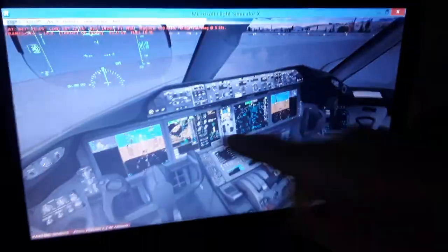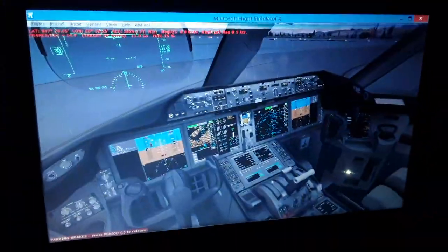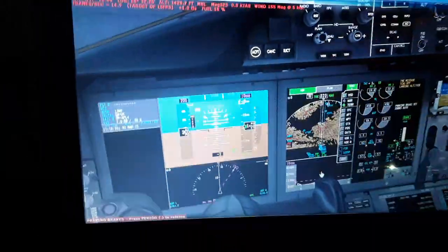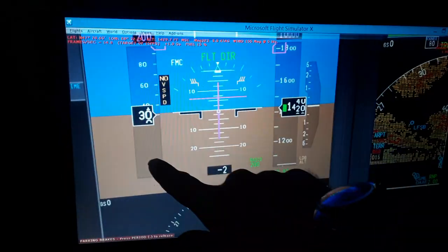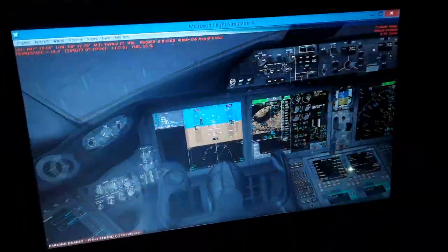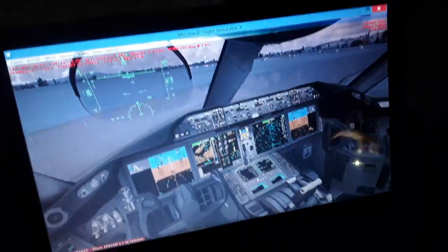As I told you, that is where the maximum aerodynamic lift occurs, also where the stall begins in flight for a given angle of attack. So you have to monitor the stall speed over here in the primary flight display. The airspeed has to be above the stall speed all the time. You will see the red and yellow indication of the stall. We need to avoid that. So we have how much fuel we have in the left and the right wing and in the center tank, 30% and 30% in the left and the right wing, 10% in the center.